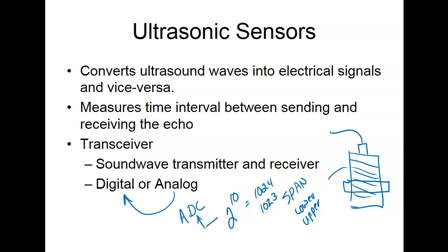The little 1214s that we have, those things have 12-bit analog to digital converters, so it would be more accurate. So it would be 2 to the 12th minus 1. What's 2 to the 12th? 4096. So it would take it and divide it into 4095 steps. I did that in my head, by the way. Y'all know that, right?